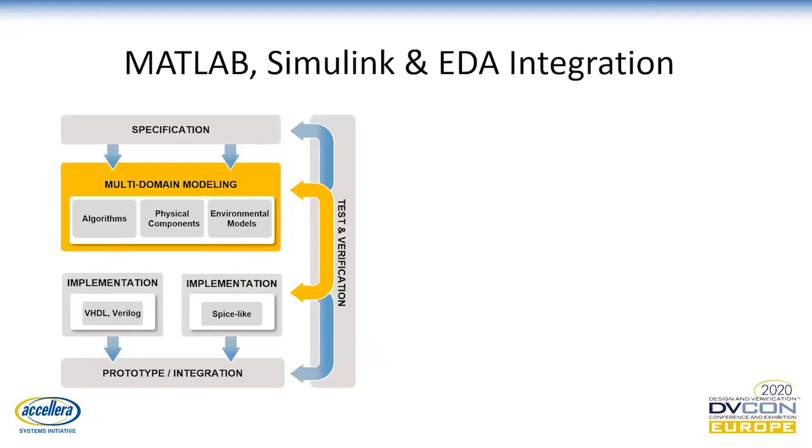So the first thing that you can do is to utilize the co-simulation functionality, in which you drive the same stimuli in parallel into your model and into your implementation, while comparing your outputs, right? So don't forget that at this stage, your model is already verified to your satisfaction. That's the part that Christian was just describing. And now it's actually your kind of golden reference. That's what you compare your results to.